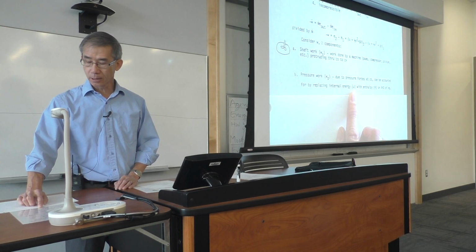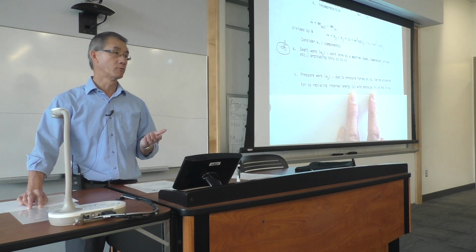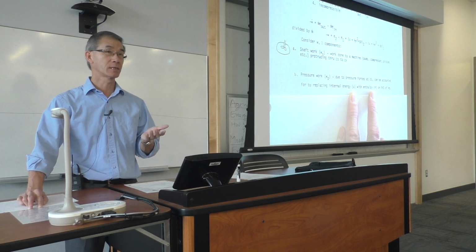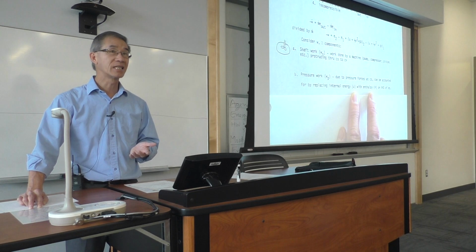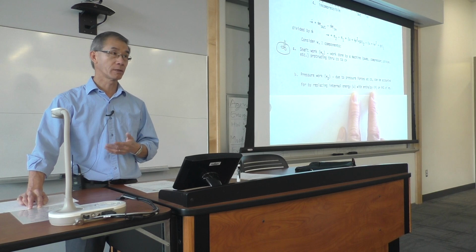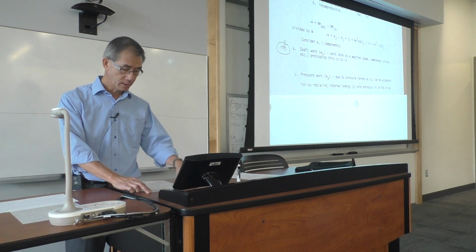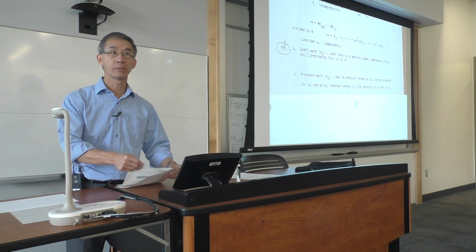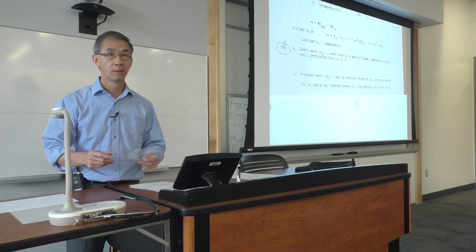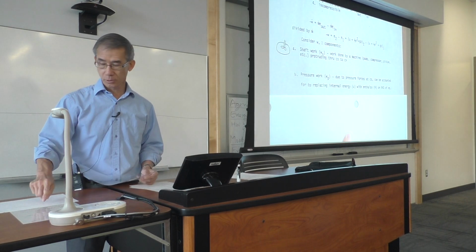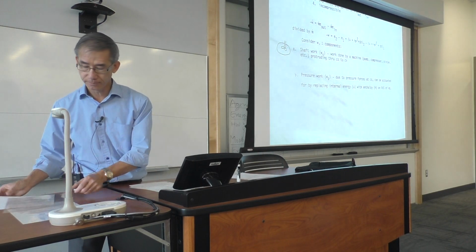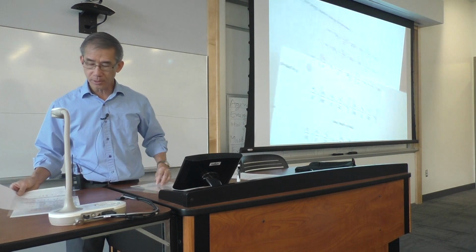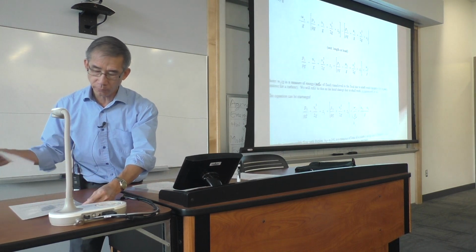Instead of using the internal energy, that flow work, which is pressure times specific volume, can be replaced by enthalpy. So H is now not the height, H is your enthalpy. How is enthalpy defined? Anyone remember that? What is H equal to? U, internal energy, plus what now? PV. That PV, pressure times the volume, is what we call the pressure work, or the flow work.